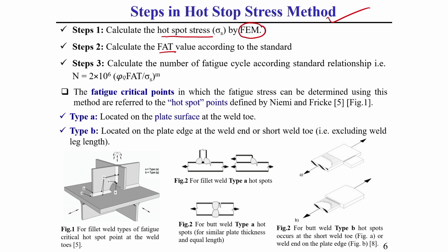And at the end, using this hotspot stress and this FAT value, we need to calculate the number of fatigue cycles according to the standard relationship given here.